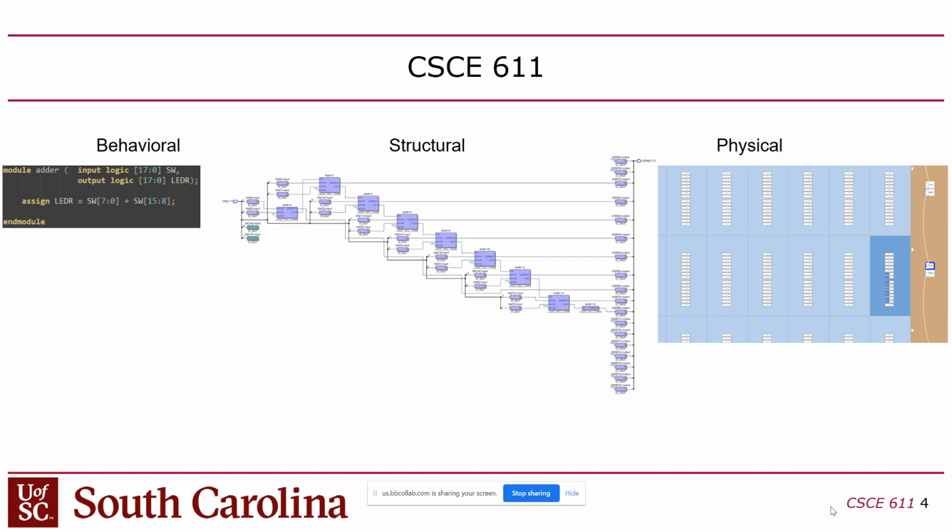So the idea is to just try to achieve a good mapping. Unfortunately, this figure is not very descriptive. This is actually a screenshot of the tool that we're going to be using called Quartus. And I've zoomed in on the actual fabric of the FPGA. Basically, every one of these boxes is a slot, and these smaller boxes are also slots, and these are slots for I/O pins. And you can see that just a few of them are filled in, like darker blue, and those are the ones where I've taken this design and allocated it on that array, right?